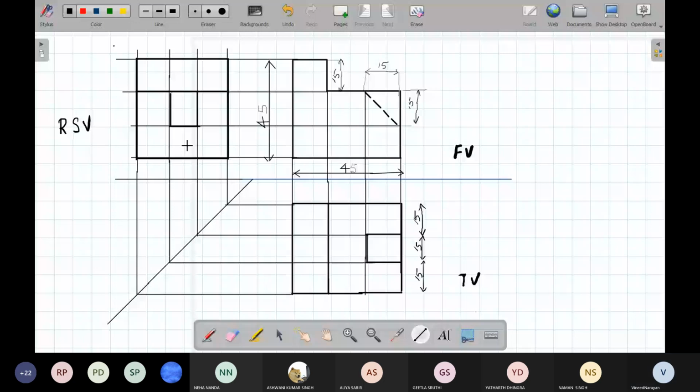So these lines are also thin and continuous. Continuous and thin. Dashed line is used only to represent the hidden parts. So please remember these points. Anybody is having any doubt? Or if it is too clumsy, when after drawing all the lines are looking the same, you can simply erase this also, no problem.